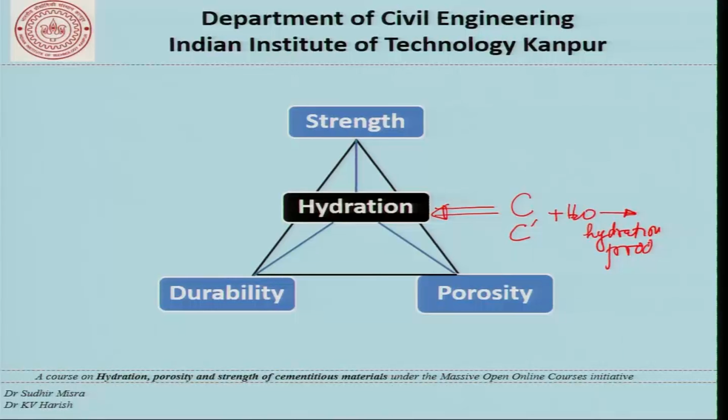Now, this phenomenon of formation of hydration products is closely related to porosity, durability and strength. And these key parameters, strength, porosity and durability, are closely related among themselves. If we want high strength, we would like to have low porosity. Similarly, if the porosity is low,